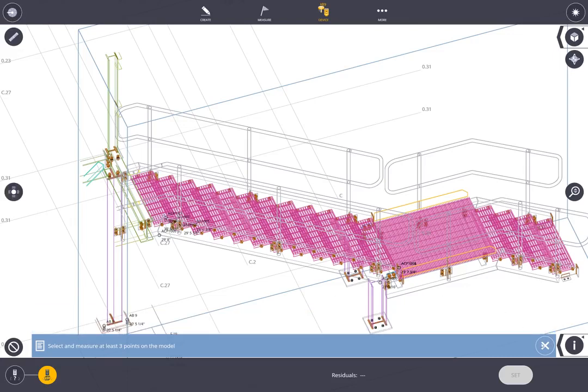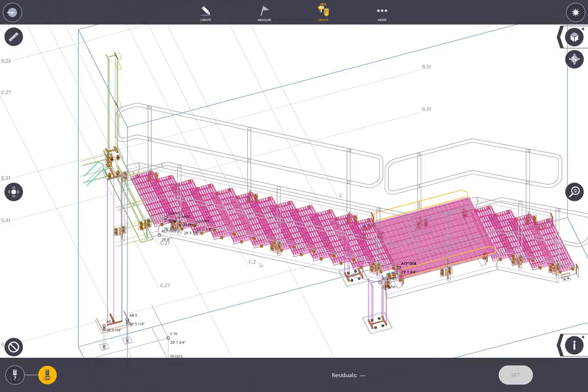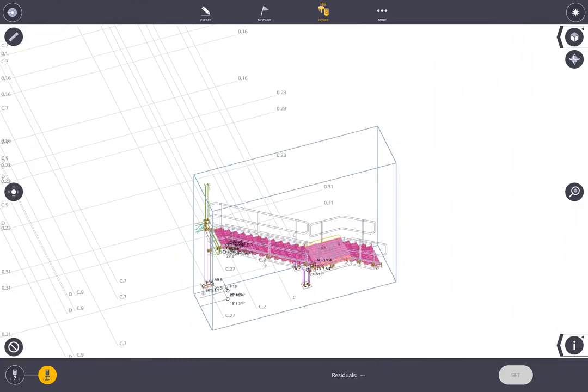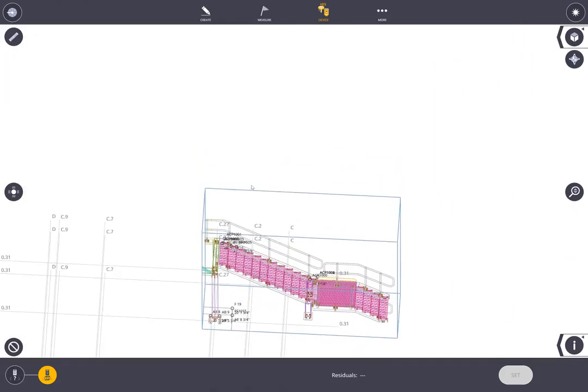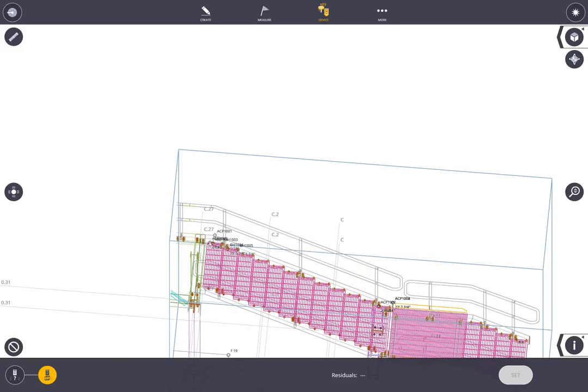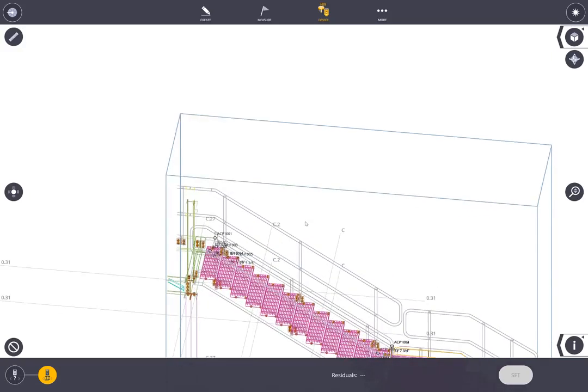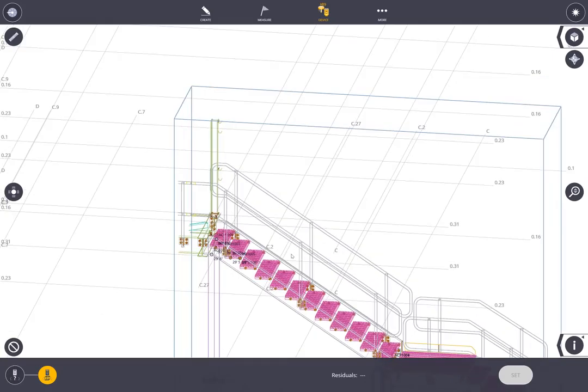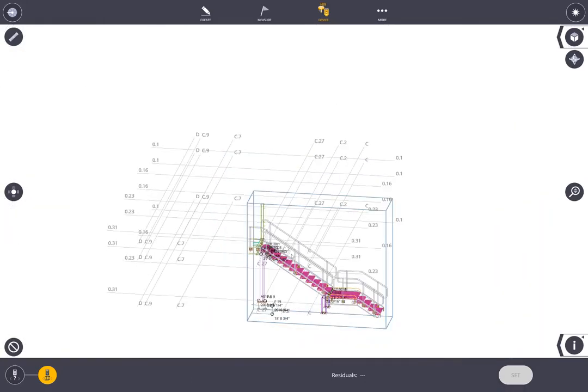So it's a little tough to fake that out on the emulator, but basically if we shot those 3 control points, the instrument would now consider that this position is laying down and that we're looking at the bottom of the stairs. And we shot those 3 points, and now we could start to lay out all the bolt holes and any other points we had created during that data prep operation. So a really convenient tool for doing shop layout or assembly out on site, or tilt-up panels or prefab items out in the field as well.